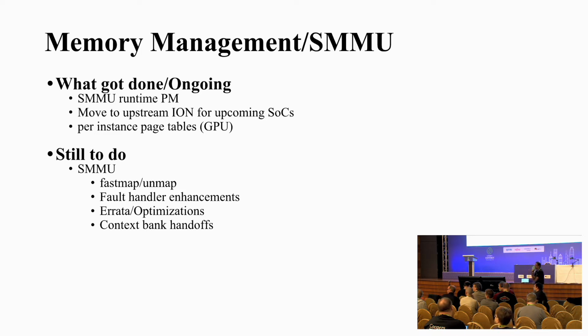Yeah, I think that's the design side requirements that come from downstream to start using SMMU. Although they are making one-to-one mappings at the bootloader level for the splash screen buffer, just when the kernel would start coming up, we needed context bank handoff in order to handle it.